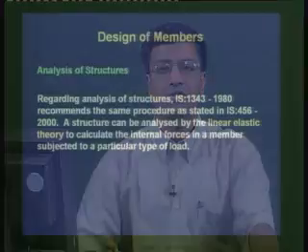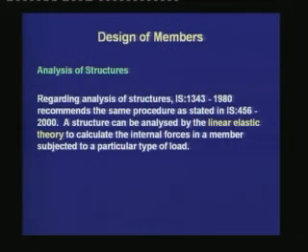Regarding analysis of structure, IS 1343-1980 recommends the same procedure as stated in IS 456-2000. A structure can be analyzed by the linear elastic theory to calculate the internal forces in a member subjected to a particular type of load. Thus, the code allows us to use the linear elastic theory for the analysis even if we do the design based on the limit states method.